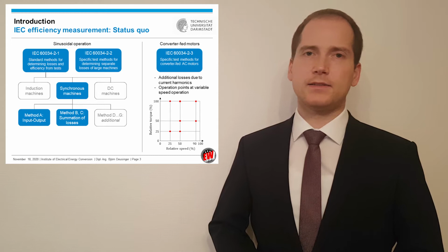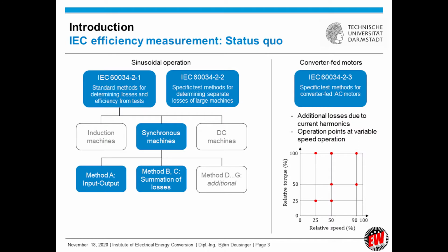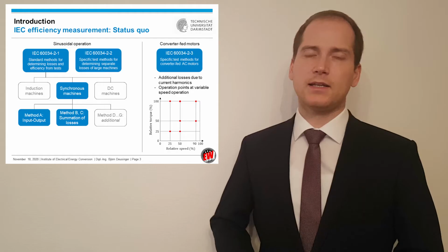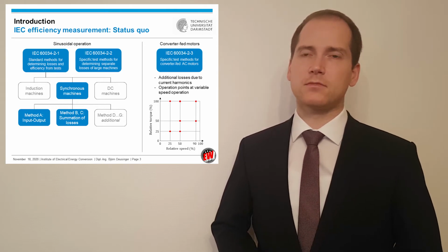On this slide you see an overview about the currently standardized efficiency determination methods according to IEC 60034-2. 60034-2-1 and -2 address the fundamental losses of induction machines, synchronous machines and DC machines. In this presentation I will focus on synchronous machines.